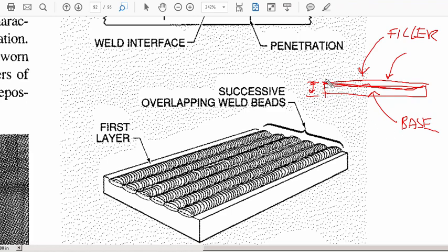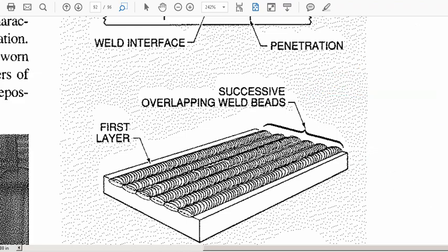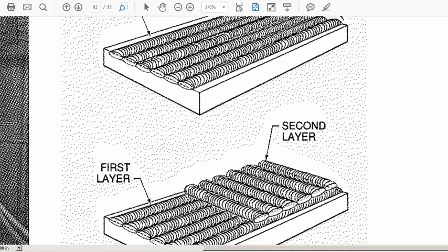And you could keep coming back, so you can do layer after layer to continuously build up. Obviously, this would take a long time if it's a large surface area, but you'll see this in repair work, especially just because of the fact that parts get worn out, and this can actually add strength back in. One of the interesting things also about the surface weld process is you can actually layer it conversely.